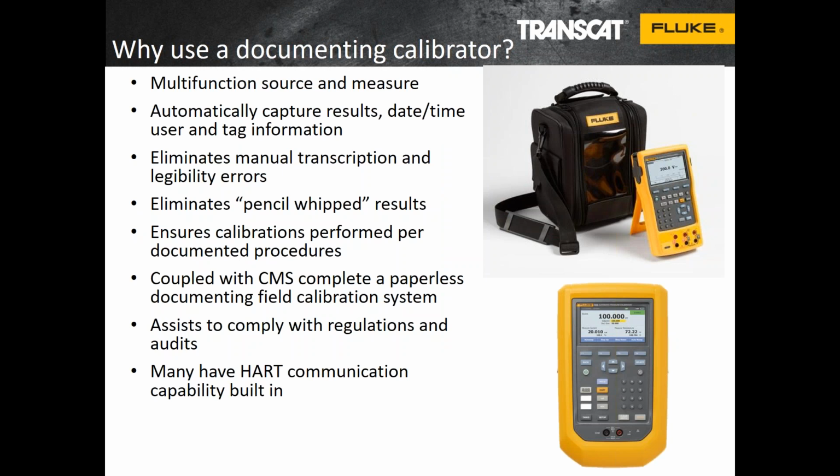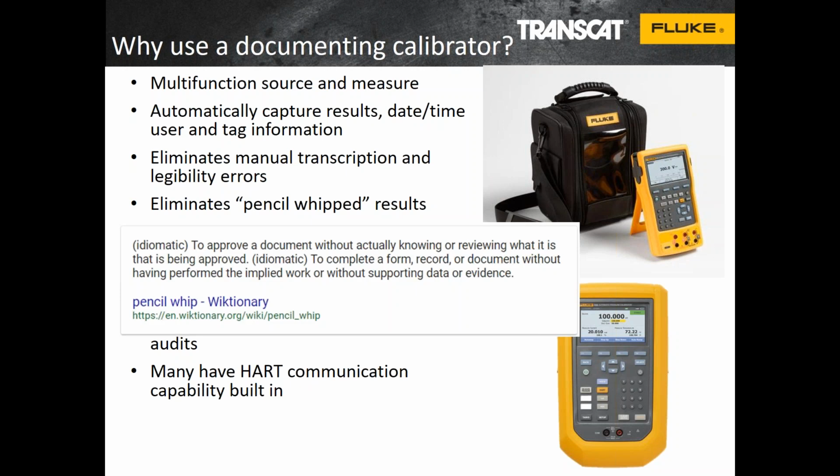So why use a documenting calibrator? They do have the capability to source and measure and have traceability. They automatically capture results, date, time, user, and tag information. They eliminate manual transcription and legibility errors, and they eliminate what we refer to as pencil-whipped results. Next. Now that's not a term that I made up.